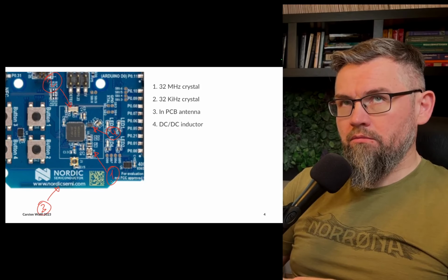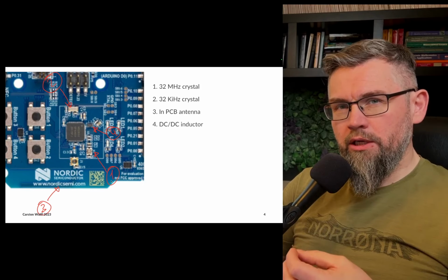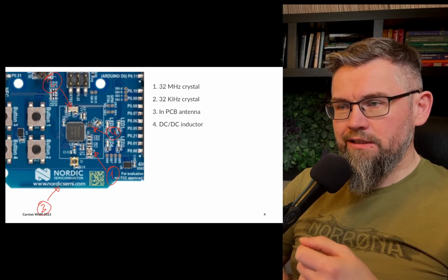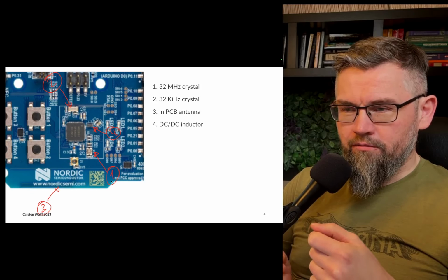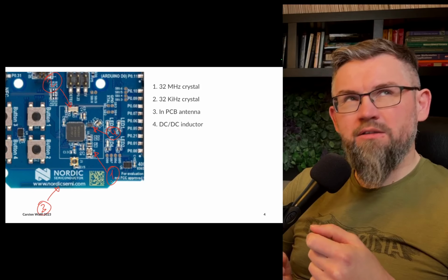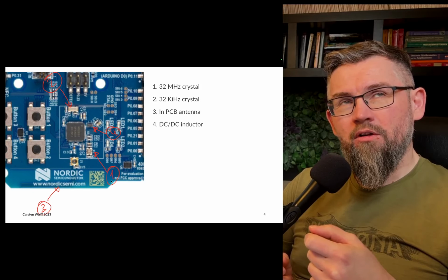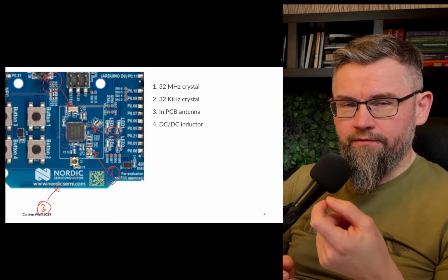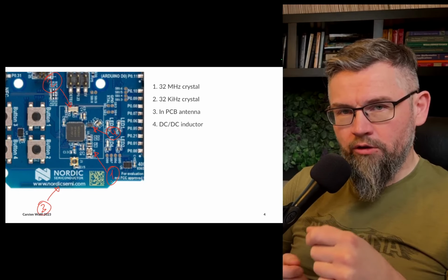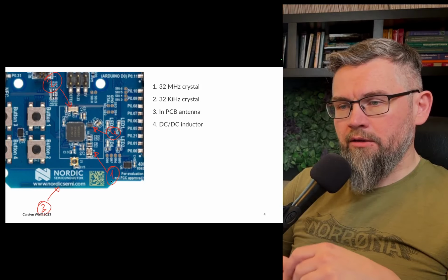And to create a really precise frequency, we need a reference, and that reference is this almost, I don't know if it's mechanical, but the crystal itself resonates at a very particular frequency as long as you drive it correctly. And it can be very precise.